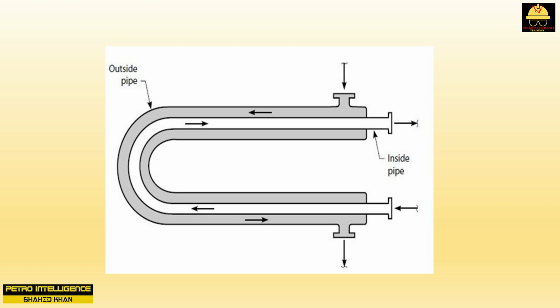Moreover, they are not subject to bypassing. The only problem with them is cost per square foot of heat transfer surface area. A single pipe or tube simply cannot have much area, typically 100 to 300 square feet. Exchangers of less than a few hundred square feet can be economically designed in a hairpin configuration. Larger exchangers are, for economic factors, shell and tube types.